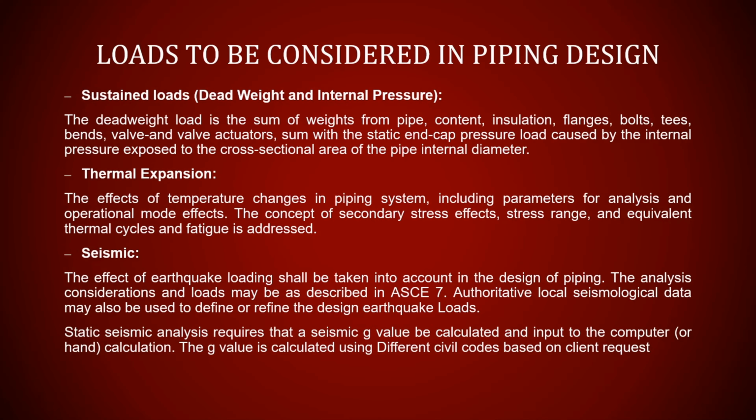Loads to be considered in the piping design. When we are performing the piping stress analysis, we need to consider these forces. First of all, the sustained load based on the code name, which is the dead weight plus the internal pressure.